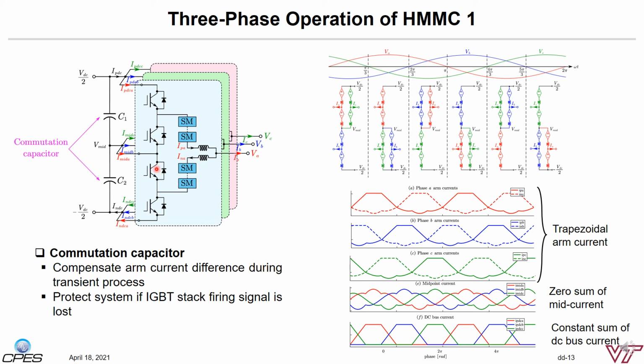Definitely, these small commutation capacitors can be put in parallel with the high voltage switches directly, so they become a snubber capacitor. Fortunately, as we only operate the high voltage switch at the low switching frequency, the switching loss from the snubber caps can be very small.